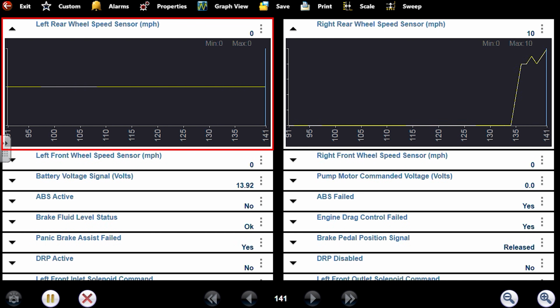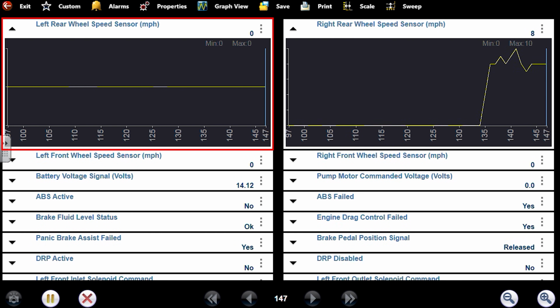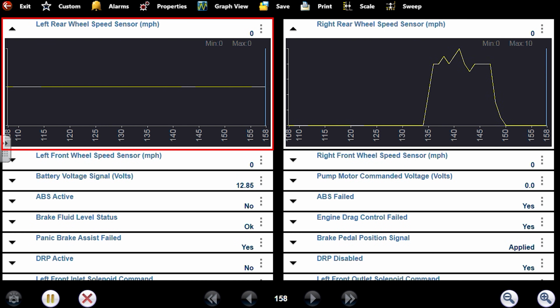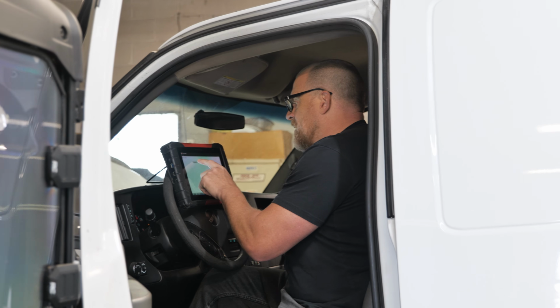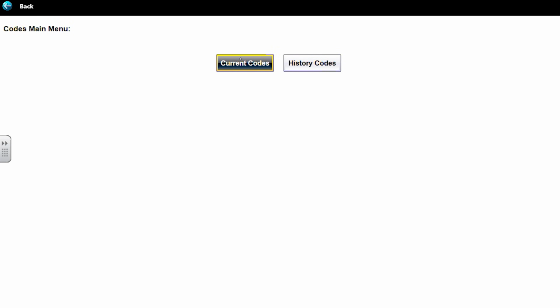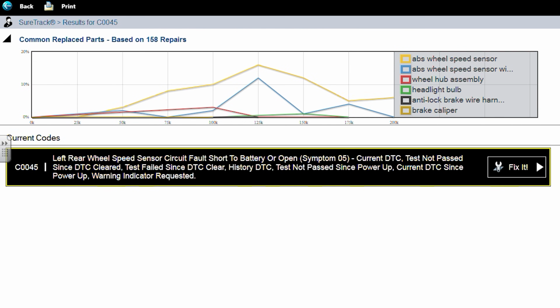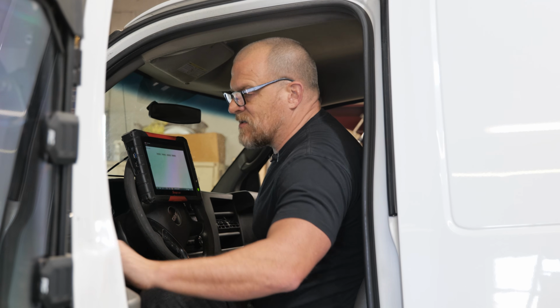How weird. So it's not a substitution, because with that unplugged I had no wheel speed signal. Let's see if we get a different code now. Oh, strange. Same fault. Or no, new faults, I should say. Oh, it's just so weird. Like, I just can't clear the code.